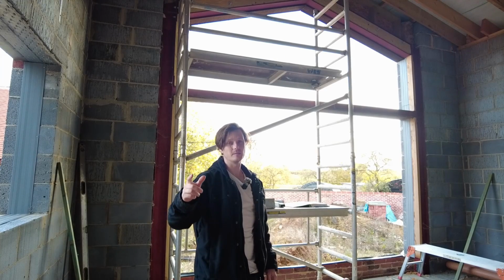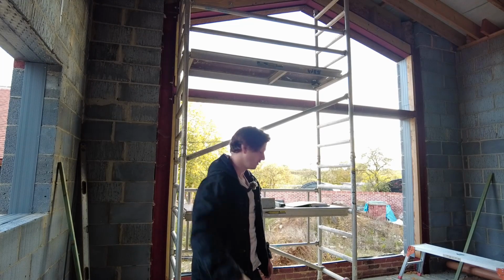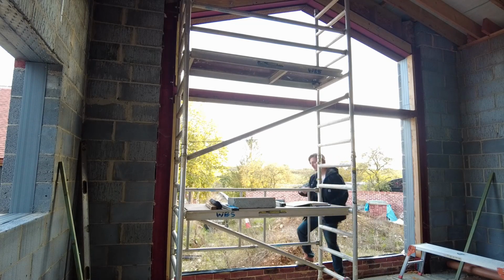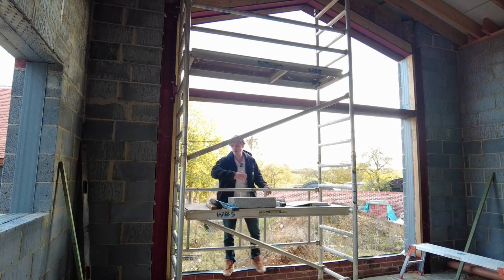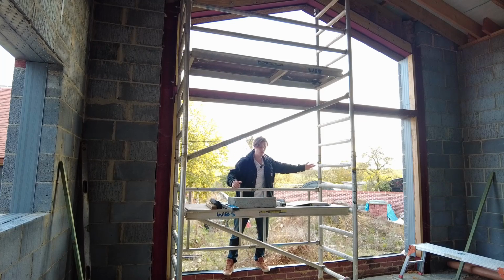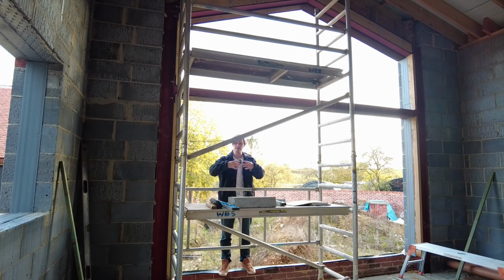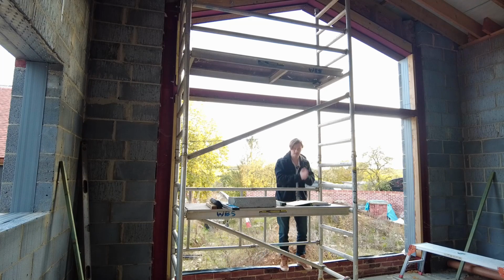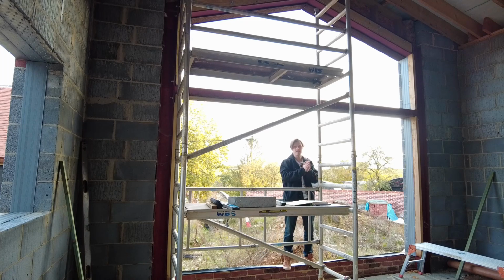Something you should consider, because the window company might not. I'm having bifolds here, so I would have a 4-leaf system. One door opens there, and then 3 fold that way. Now the floating mullion on this door is quite thick. That naturally means that it throws off these other mullions. The center one isn't bang on center for this.